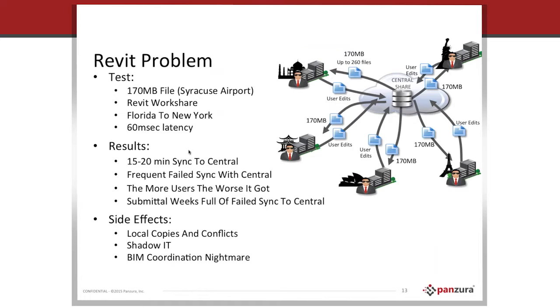So now that's kind of the simple scenario where you open a file, it locks, and it works. Revit's a whole different animal because I'm sure those of you who use Revit know that Revit allows multiple people in the same file at the same time. Again, Revit was originally built to work on a local area network. And so it's still designed and works on that basic premise. Even with solutions like Revit Server, it's basically still doing the same operations.